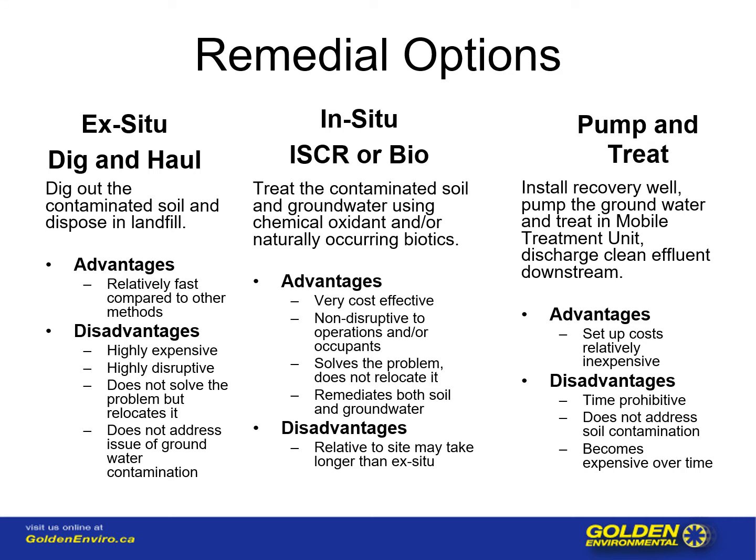One installs a pump and treat system downstream of the contaminated area, and then as one injects an amendment upstream, that depressed water table at the bottom of the contaminated zone naturally draws the amendment through the subsurface. This could be advantageous if one is looking to remediate soils underneath large industrial buildings and wants to speed up or increase the flow of the amendment underneath the building.